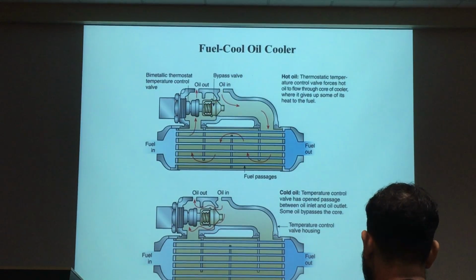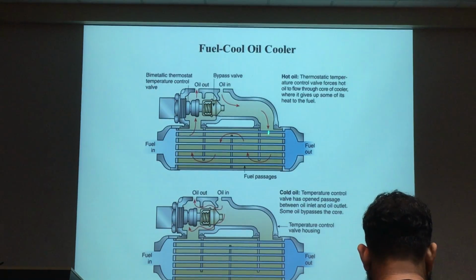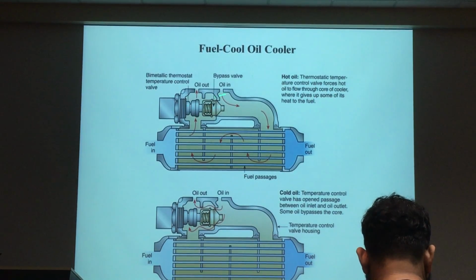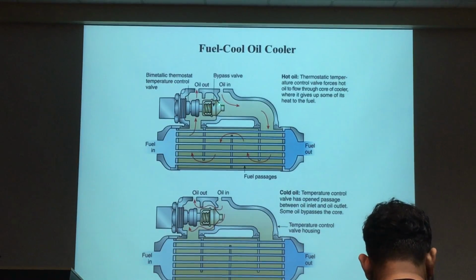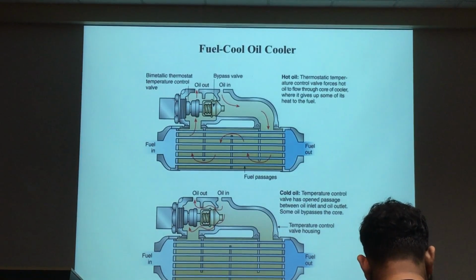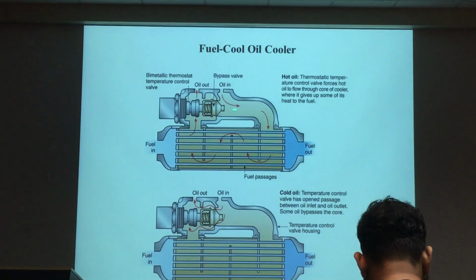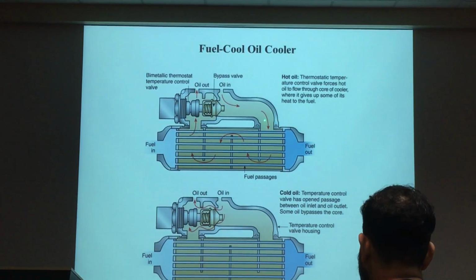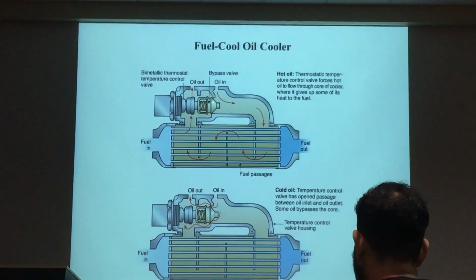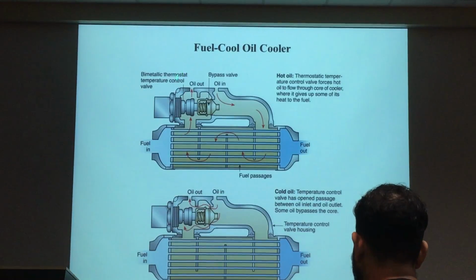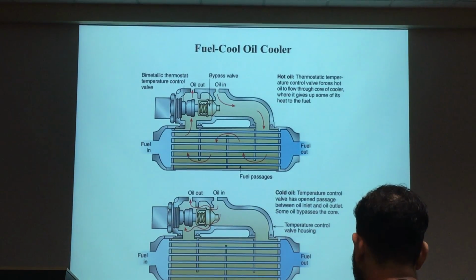If the oil is already very cool at the inlet, there is no need to cool the oil. So all the oil will be bypassed by this thermal stage here. If the temperature is cold, the spring retracts, the valve opens, and the oil will bypass. It's a real concept. If the temperature is high, you close it back, the oil will go in. You cool the oil, maintain the oil. Another one, when this one is clogged, the pressure will build up. You push this door open, the oil will bypass. So nothing happens to the oil system.